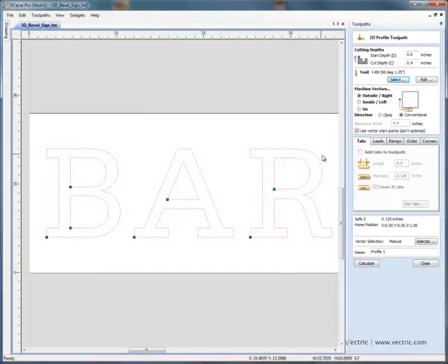We're going to cut the chamfer on the outer edge of each letter to a depth of 0.4 of an inch. We're going to machine around the outside, as I've just said. And if we specify from the options menu, if we click on corners, we're going to machine sharp external corners and also sharp internal corners. So for example, in the corner of the B there, we want the cutter to be lifted into the corner.